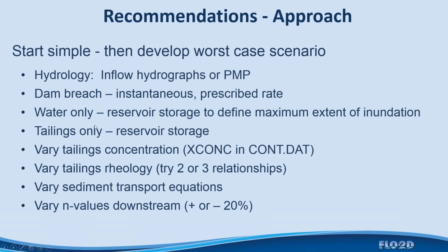Now, as far as an approach goes, I would start simple, of course, and then develop a worst case scenario. So you start with water, and first you develop your hydrology. You need an inflow hydrograph or maybe a PMP to your dam breach model, or maybe it's just a sunny day failure. It could be either one. In terms of the dam breach, you can do instantaneous or prescribed rate. I recommend those. You can also do the erosion breach modeling, and there is a typical dam breach webinar and PowerPoint presentations for this. You just have to search around on the website for it.